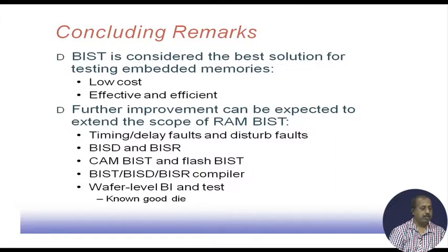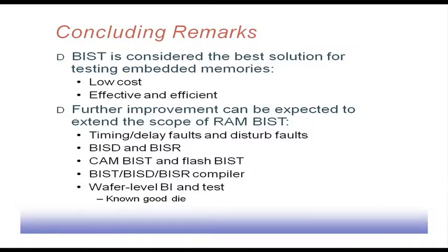Then built-in self diagnosis, BISD, and built-in self repair, BISR: these are the two directions where work is going on, because diagnosis will diagnose the particular cell which is faulty, and repair will try to repair it in terms of maybe replacement and all that.